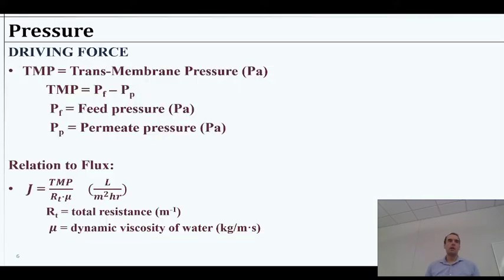Okay, so let's talk about the driving force behind operating a membrane. That would be our pressure. I think we talked about it briefly last time that you can use gravity. You could potentially draw a vacuum. You have some limitations there for the vacuum. You can only have as much pressure as you have atmospheric pressure if you're going to do that. But you could just take a pump and just hammer on the water until you get a really high pressure. Water is practically incompressible, so that works pretty well for pushing it through a membrane.